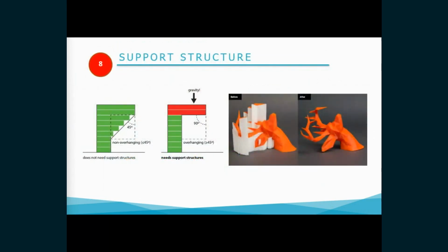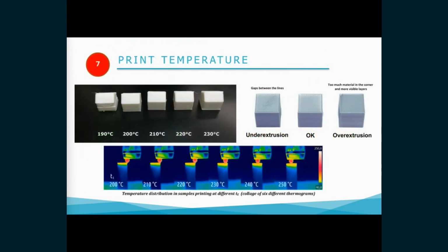This temperature needs to be reached for proper printing, and since each plastic has a different glass transition temperature, every filament needs to be printed at a different temperature.